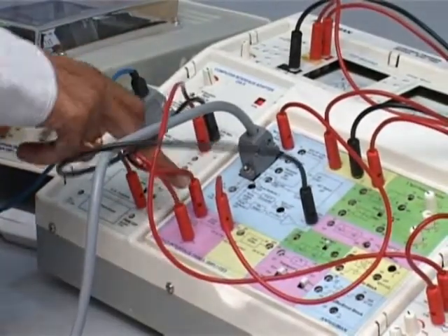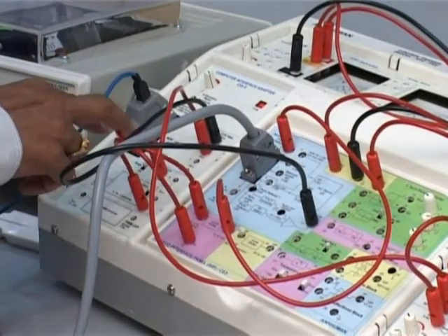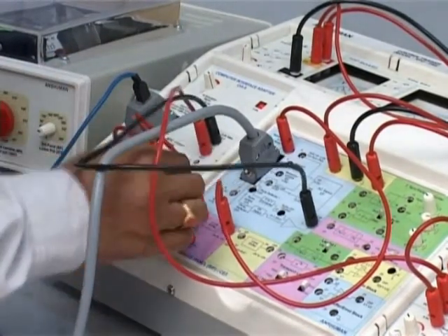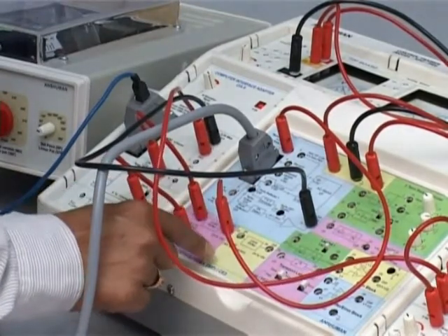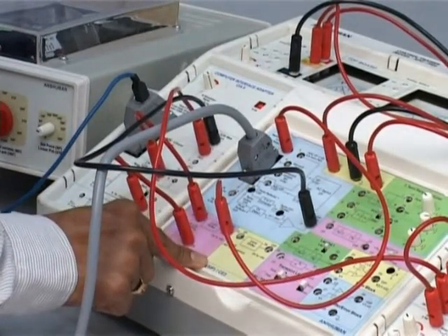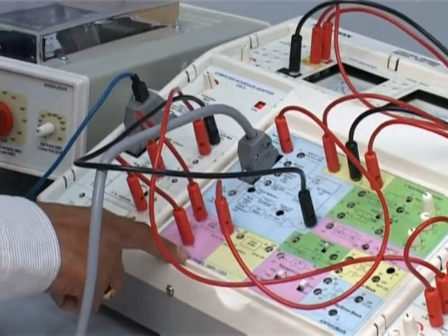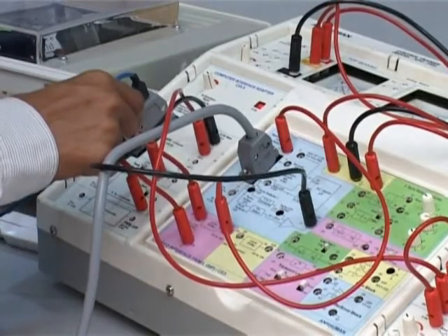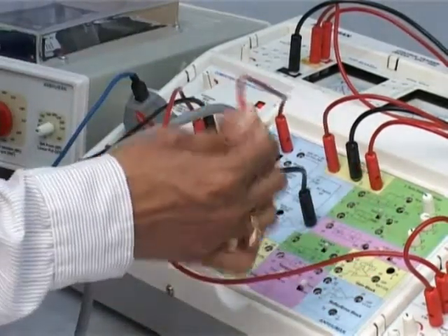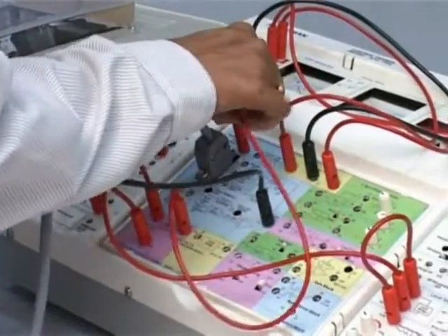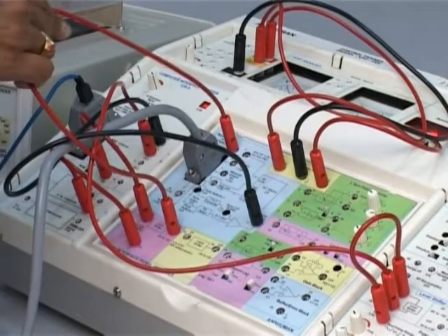Here connect the DAC output to the level shifter. DAC output from 5 of the computer interface panel to 31, the level shifter input of the CE3 panel. This is because we are doing the digital PID experiment, hence the DAC output has to be connected to 31, and the level shifter output has to be connected to the servo interface panel 4 number tag of the CE3.